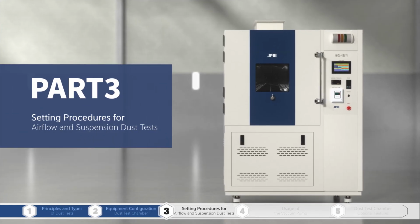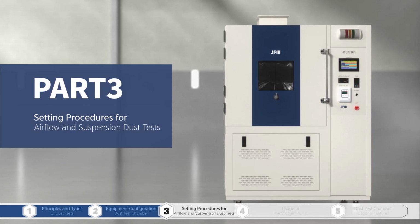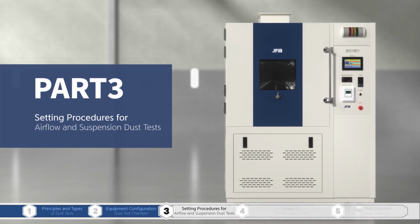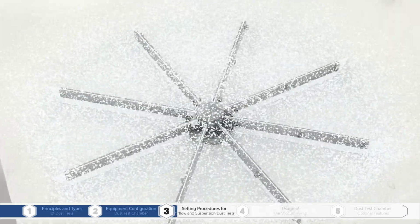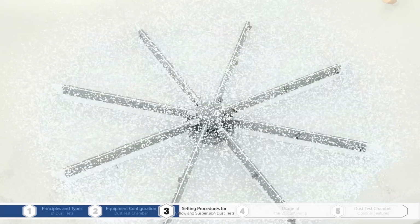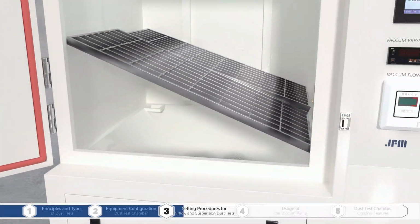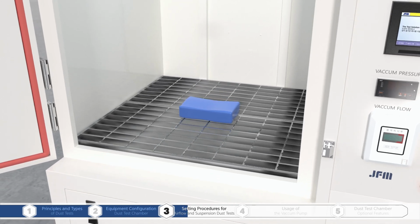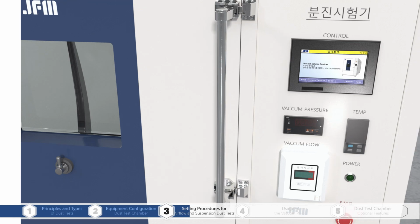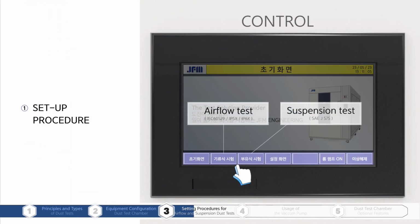Part 3. Setting procedures for airflow and suspension dust tests. Let's explain how to set up the dust test. First, load the talc dust, approximately 2 kilograms per square meter, into the chamber and check its condition. After securing the sample, close the door. Then, choose between airflow and suspension tests.